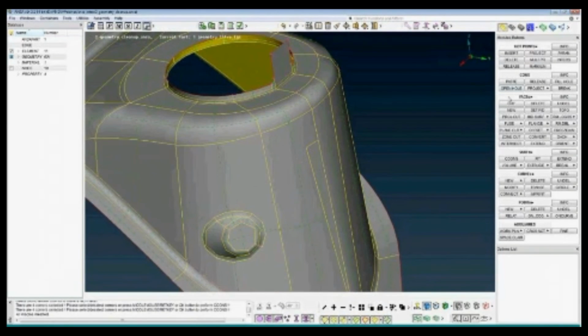This can also be done in the top of the menu. With the cut function, we cut between 2 points, left mouse button, you uncut with the right mouse button. When the yellow line disappears, it means that the two faces that are connected use the same surface. If you remember, when we created the face at the crack, we used the existing surface. Then the line is deleted.